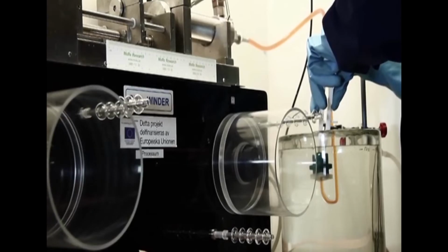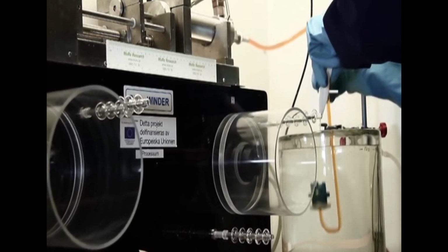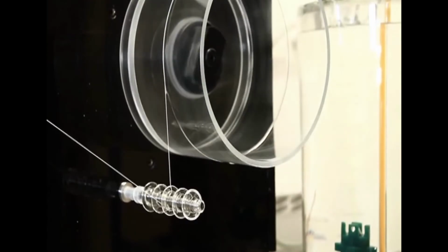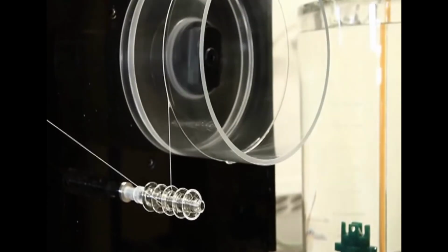And for this reason, we need spinnerets of high quality and which are corrosion resistant, because the spinneret has to be placed in a chemical bath, so that it is able to pass the polymer liquid through its holes into the chemical bath. So, in order to resist that chemical, the spinneret has to be made of some precious metal, which again requires huge investment on the part of the manufacturer.